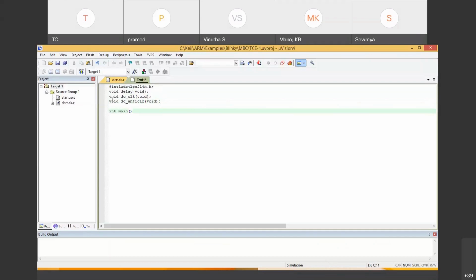So now how do I start? I declared all the three functions like this. I'll start int main. So what should the main program have? Which pin select I should use? Since I wanted to use P0.30 and P0.31, I should use pin select register 1. 0 is from 0 to 15, so 16 to 31, we have pin select 1. So port 0 needs two pin select registers. So pin select 1 is equal to 0x, all 8 zeros, that's it.